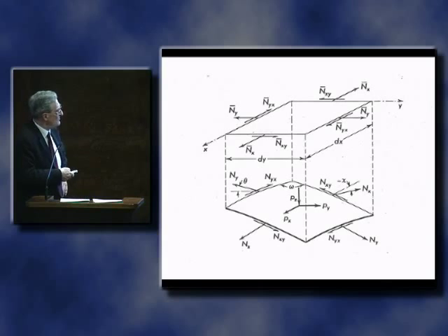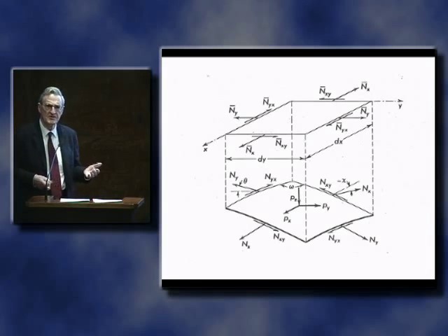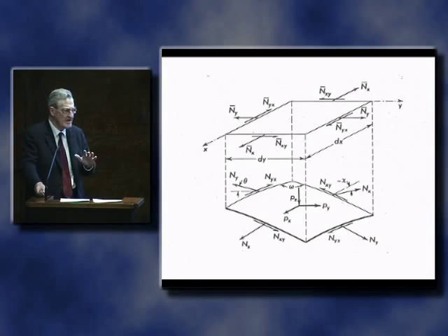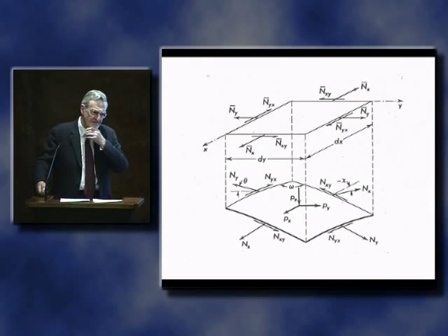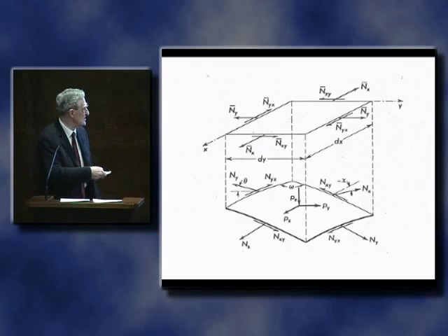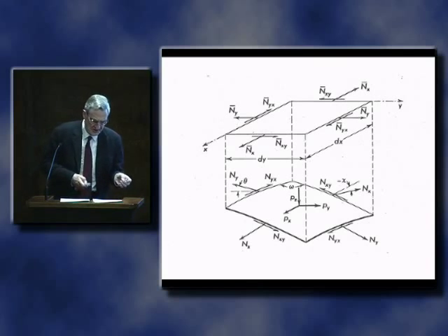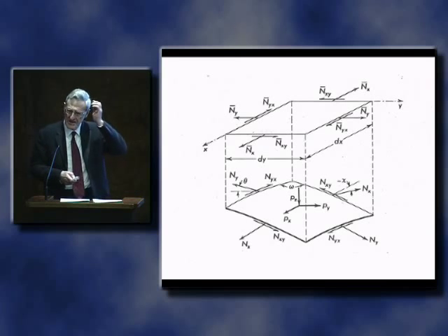But what those forces do is to produce stress resultants, very much like the 2-dimensional stress one gets in elasticity analysis. That is, you can have a pull in one direction, the y direction, a pull in the x direction, and a shear force on the surface there. But most importantly, the theory assumes that there are no forces transmitted through the shell across these surfaces. These are the only forces acting there, and that there is no bending of the shell. So this is a severe restriction on the analysis, which we must take account of at the end of the story here.